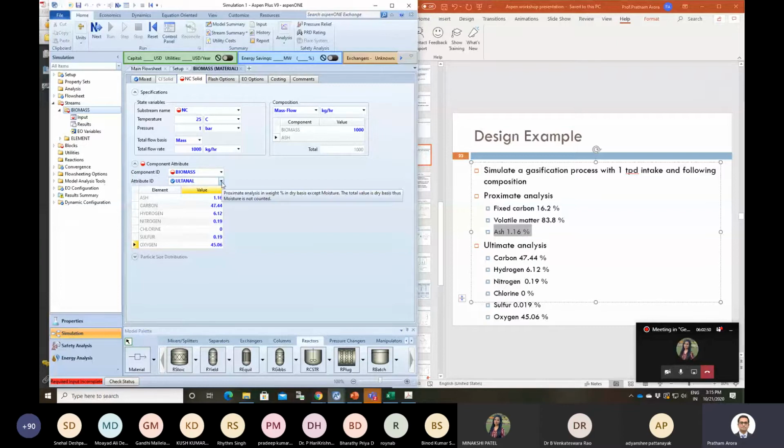What is it? It's the sulfur analysis. So I go to the sulfur analysis. And since this composition is not available to me, I can put in 100% to pyritic and then 0, 0 for both of the others. And then you can note that all of these have turned blue, which means all the things that are needed as an input have been provided. So this is how my input streams are complete.